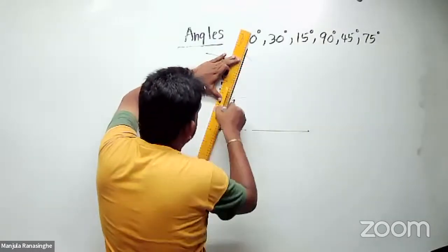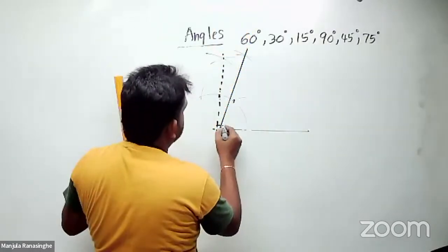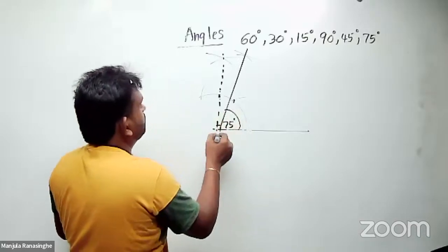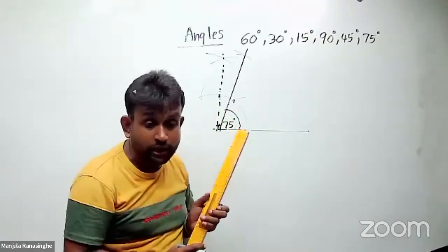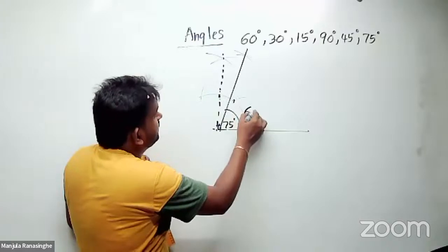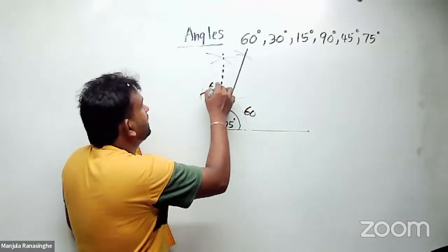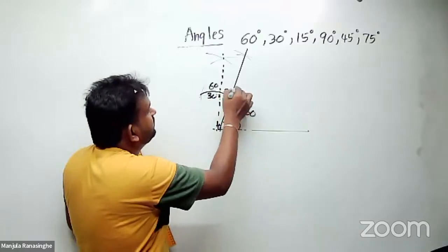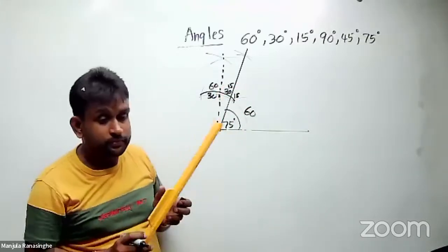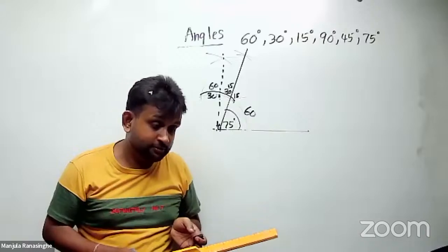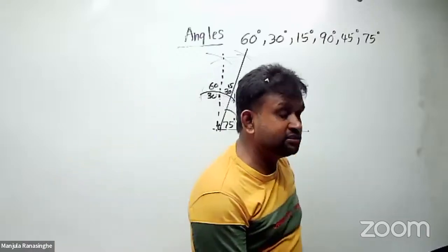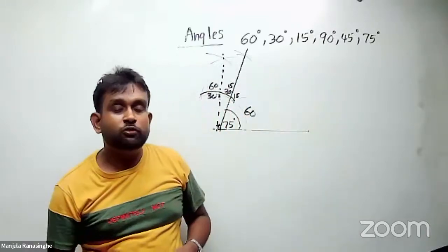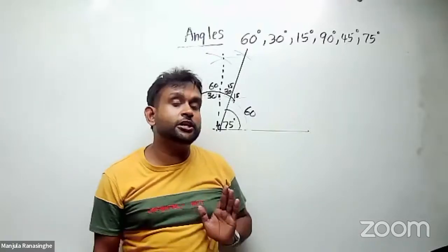So that is 75. So this is called approximately 75 degrees. Right. So how does the concept work? Here 60, then here 60 is taken and bisected: 30, 30, and then 30 is bisected like 15, 15. Okay, that is how you get it. Now the angle creation is done. Now we will do the triangle creations.